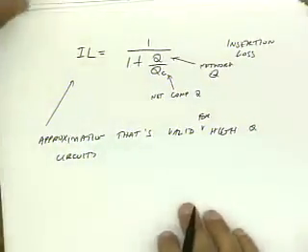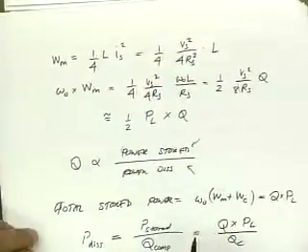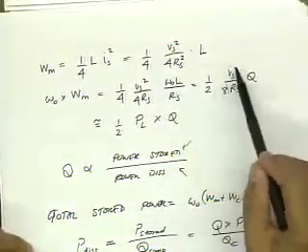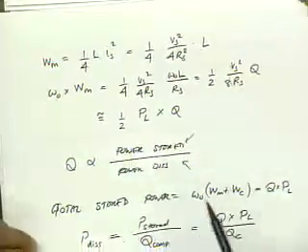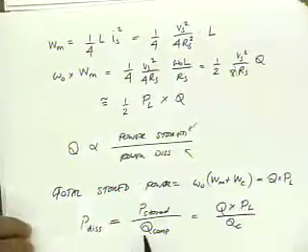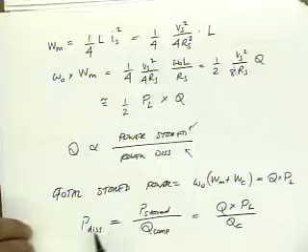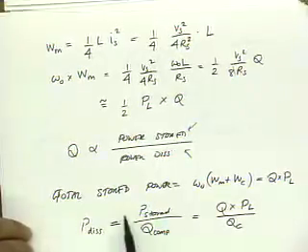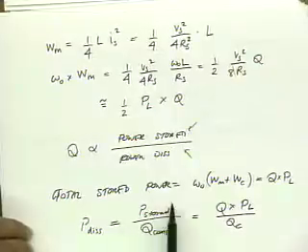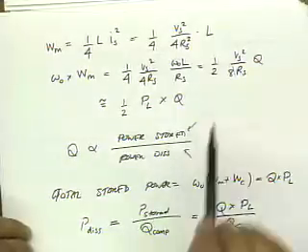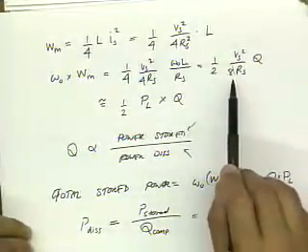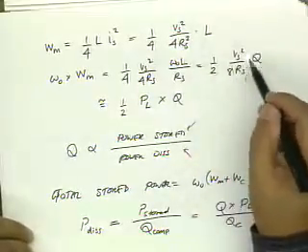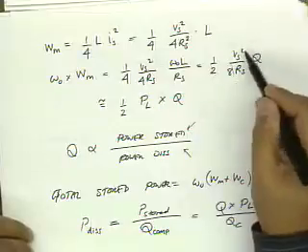The reason it's an approximation is I made a lot of assumptions here. The biggest assumption at this point is assuming that the power dissipated is simply the power stored divided by the component Q. Even though this is exact, I don't really know the power that's stored that accurately. I made an assumption here that this is roughly the power that's stored, because really the power that's going to the load is not really this.